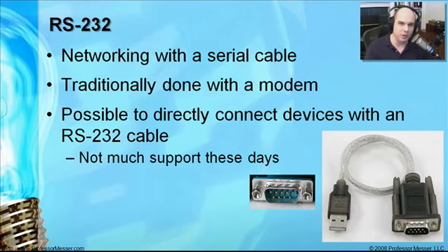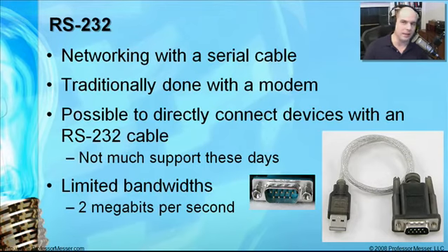All a modem really did was just extend the capabilities of an RS-232 cable. Well, if you just get rid of the modems and connect them right to each other, it's really the same type of thing. It's very difficult to find software these days that will support a network connection between two devices. But if you try to find some legacy software out there, there is some that can do that.